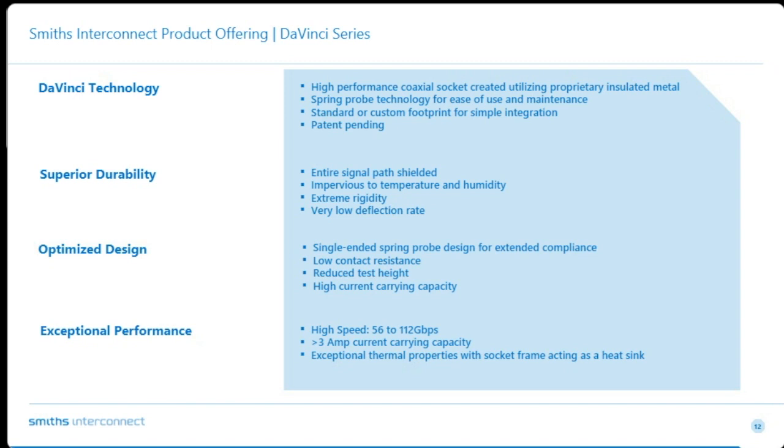Additional benefits of this are high structural rigidity. We see very low deflection rates on large pin count sockets, and the thermal transfer away from the probe array is superior to a plastic socket. But we can utilize a single-ended spring probe design for extended compliance, low contact resistance, good current carrying capacity, and ease of socket probe maintenance, as in a standard vertical spring probe socket. So DaVinci is well adapted for the high volume manufacturing environment.